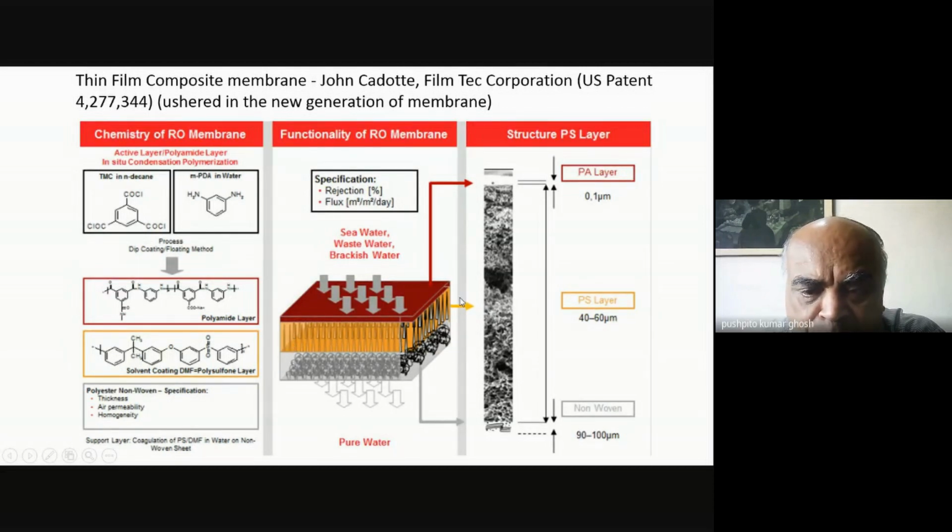make a polymer, and this polymer is typically a polysulfone polymer, very similar to the way what you saw that cellulose acetate was made. You dissolve it in a solvent like dimethyl formamide, and then this is passed through rollers, and a thin layer of this polymer gets stuck on this fabric, and then finally after it comes out, it is gelled by passing it into water.